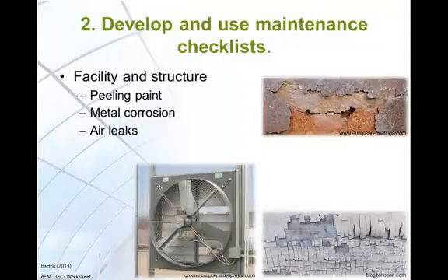Check for air leaks. Air leaks may be present around vents, fans, and doors. Weather stripping can be used to seal them. Check for holes in the glazing. Lubricate fan shutters so that they do not stay open. A partially open louver may allow several air exchanges per hour. Inspect where pipes enter or exit through the greenhouse walls for leaks.